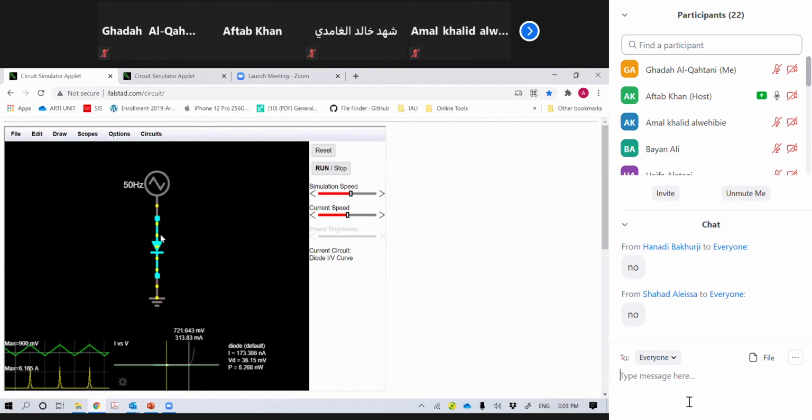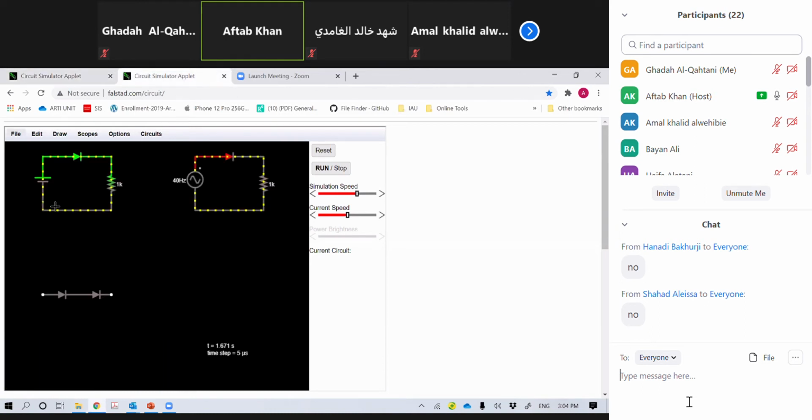So as it reaches here, current quickly passes through this diode. And again, because it's a triangular periodic wave, now it is going back. So the maximum value is here, and what is the maximum value? I can see it is 8. Now going down, now increasing like that. So that is the VI characteristic. Also, I can show you some other graphs and circuits.